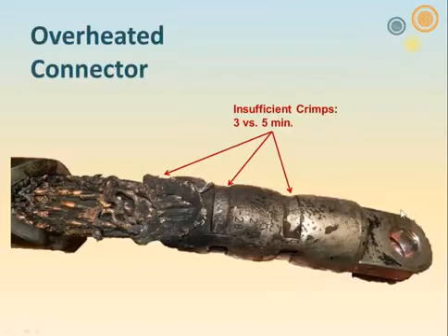This is the bulk insulation. All this area, the cable adapter, this is all bulk insulation here. What stress are we going to allow here? Now, let's say for the sake of argument that this connector, we want to have no more than 120 volts per mil. By the way, I think better in volts per mil. It's difficult for me to think in kV per millimeter, so I will only be talking in volts per mil. We're saying that we have a requirement that anywhere in this bulk insulation we cannot exceed 120 volts per mil. That's not the end of it.